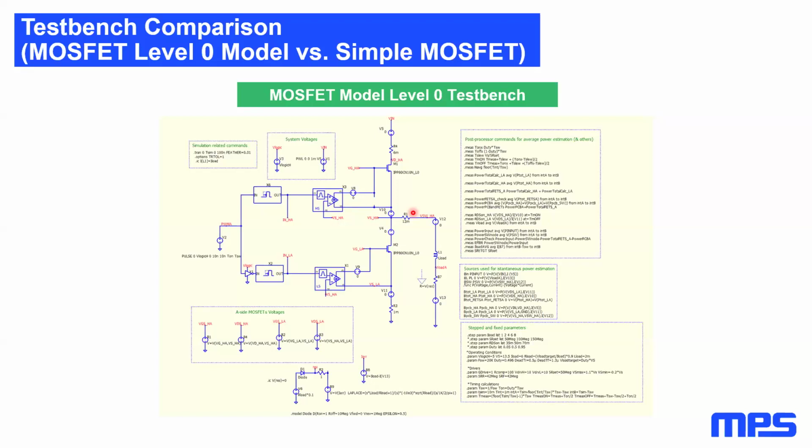An effort has been made to make sure that the DC settled value of the load current is regulated regardless of the power dissipation and regardless of the duty cycle. This is done by controlling the load resistance with a very low bandwidth feedback regulation loop. And this load current is a modeled effect of what could be the motor torque, together with a typical DC motor inductance.